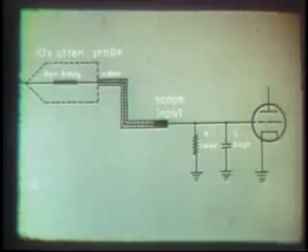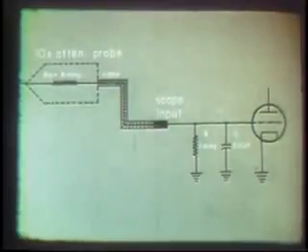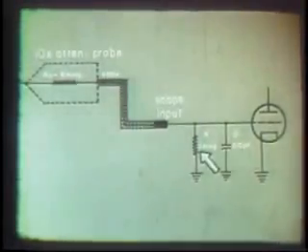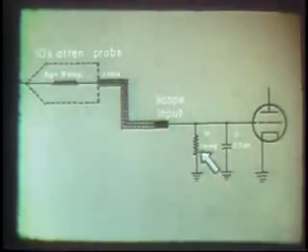Notice that when the probe is connected to the scope, a 10-to-1 voltage divider is created, just as in our earlier example. Notice also that there is a capacitance C which shunts resistor R. This tends to reduce the high frequency response.